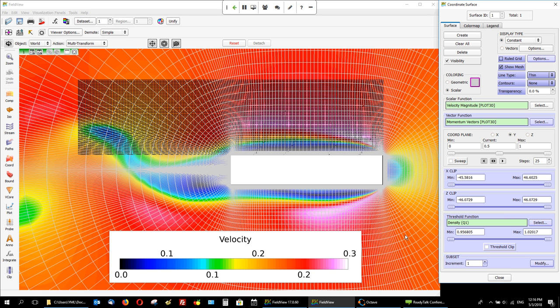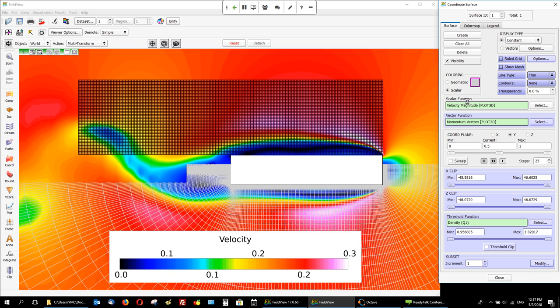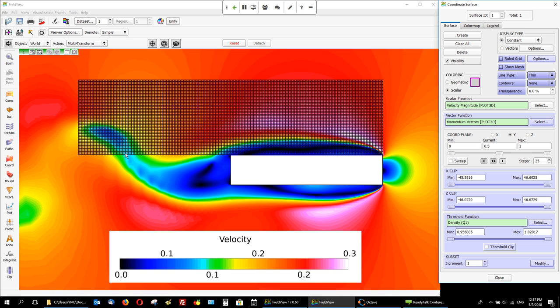So this is a potential problem when you do an SVD analysis. If you want to do it based on this computation mesh, you will have to use some weighting factors to account for the surface area of each one of your faces. Or another approach, and that's the one we're going to use here, is to have a Cartesian mesh, the one in black here, that we've imported for you to see, and this is the one that we're going to use for resampling.